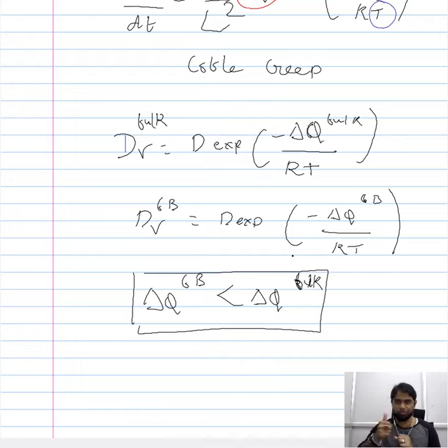When you apply a tensile load in one direction, there is a complementing compressive load along the other direction because of the Poisson's effect, and the influence of stress on the concentration of vacancies depends on the sign. The tensile stress increases the concentration of vacancies, while the compressive stress decreases it.